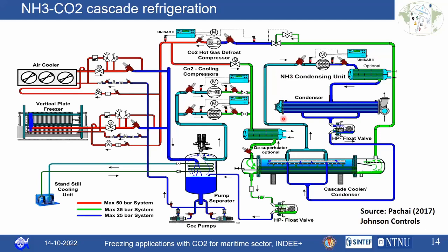At the top cycle, on the right side, you have the ammonia system or the ammonia top cycle, and you will have the screw compressor. We'll mostly be preferring screw compressors so that you can have the benefit of liquid injection to reduce the temperature of the screw compressors.